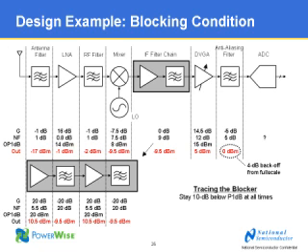Now, you may have already answered this question, but just to summarize, can you use a variable gain LNA? That's a good question, actually. A variable gain LNA would ease some of the burden on the DVGA. However, in these systems, especially in the normal condition, there is a lot of emphasis on noise figure. And variable gain LNAs generally do not provide the same level of low noise figure that's needed as fixed gain LNAs. You will compromise performance. That's why you generally don't use it.